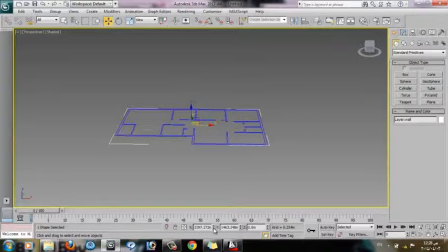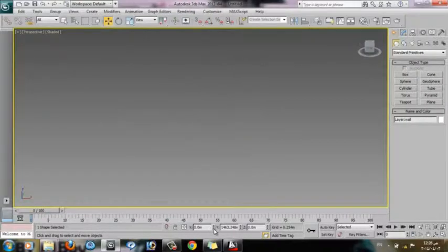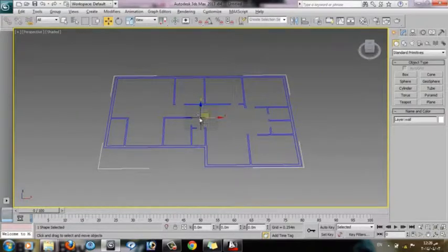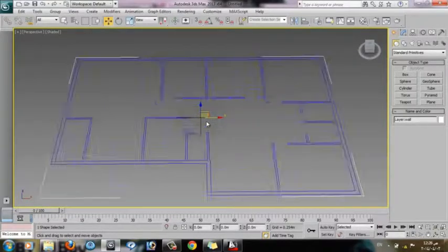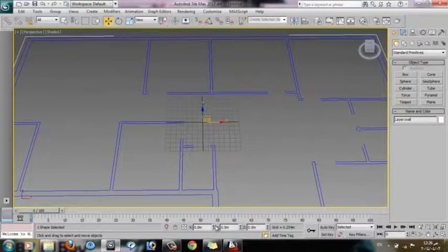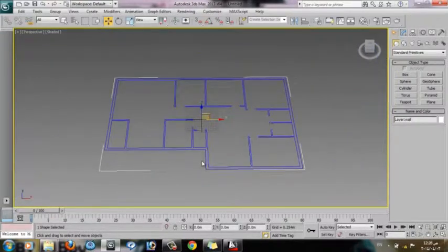If I right click with the mouse here, it will make it 0 of x, and right click on here, so my body will be on the grid. If I press Z now, I'll find the center of my body at the center of the grid. Right click just makes the arrows go to the smallest number, which is 0 here.